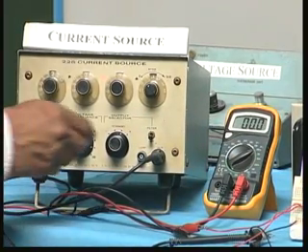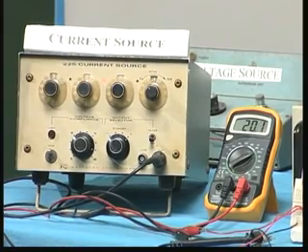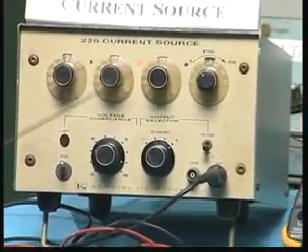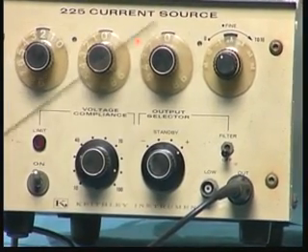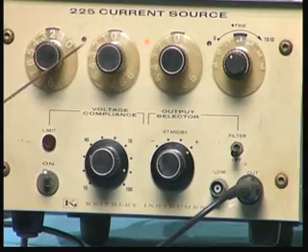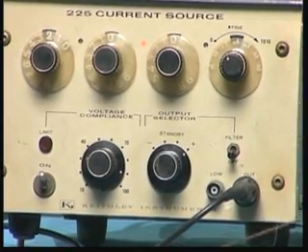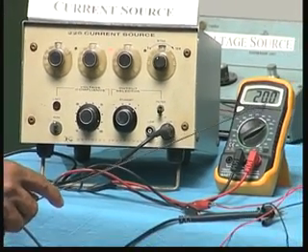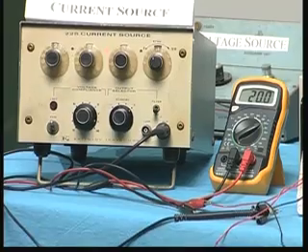Now let us try to apply the current. I do not know whether you are able to see the dial. It is 2 here, it is 0 here, and this is the decimal point, and therefore 20 point, that is microamperes. So it is 20 microamperes, and that is the current, and you can see here it is in the 200 microamperes range and it reads 20 microamperes. So this and this are perfectly matching.